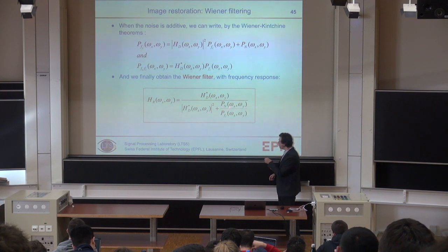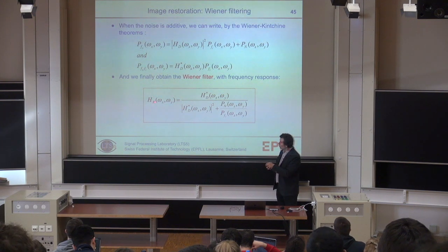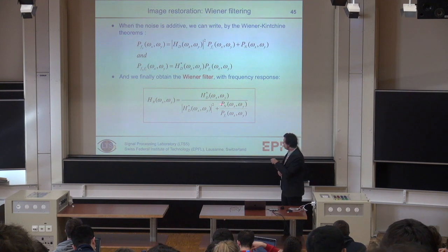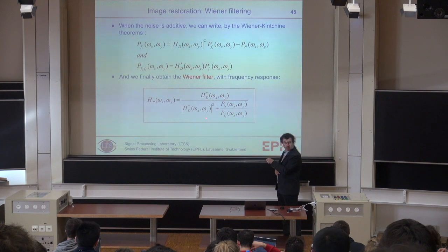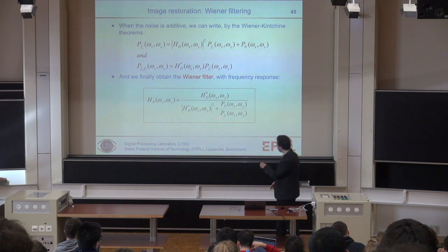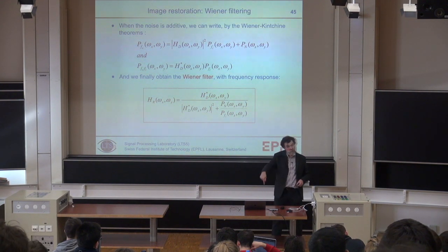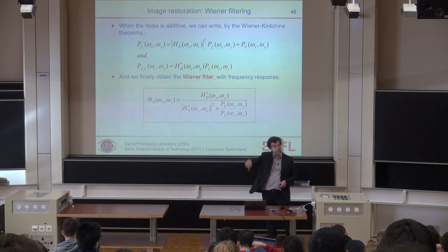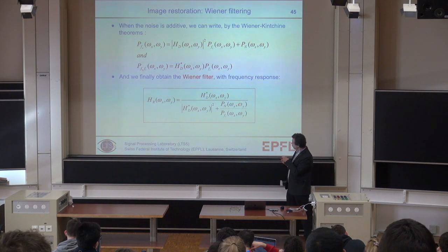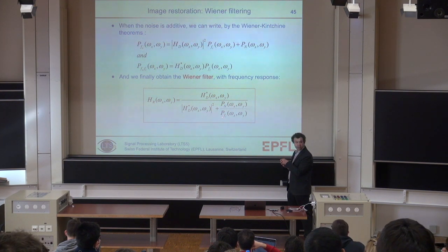And if I have a little bit of noise, the value of the Wiener filter at a given spatial frequency, so for each frequency, will basically say, no noise, do the inverse filter, but the more noise I have, the bigger this term will be, and will put the value of my filter down to 0. Because this will become big as compared to that, and will push the value of the filter down to 0, down to something small. And what you see there is, for the given frequency that I am interested in, the ratio between the power of the noise and the power of the image.